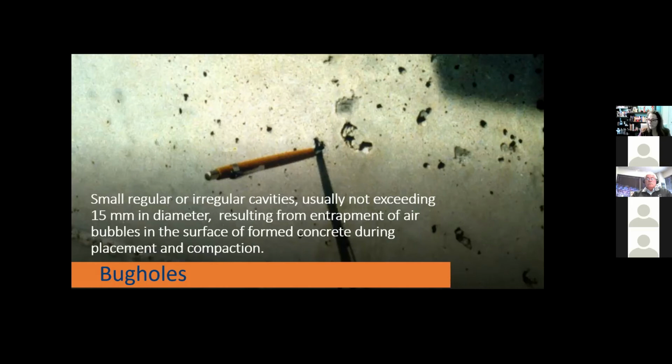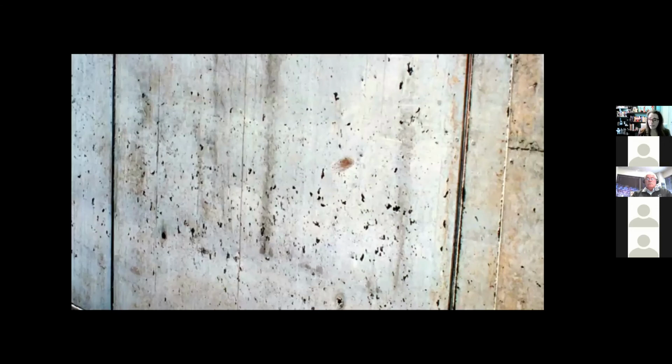They'll use products such as self-consolidating concrete to overcome bug holes, but you can change up your mix too. Look at your air content you're generating, look at your form release agents, and then when necessary, yes, you can parge your surface. If it's a thing that needs higher impermeability, then you might need to patch your bug holes. Specifications should list their requirements for repair and aesthetics within them. That might involve a mock-up, so we all have the same expectations. Hopefully that makes sense to everyone.